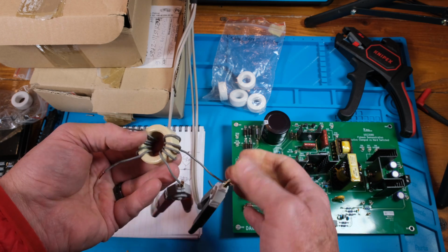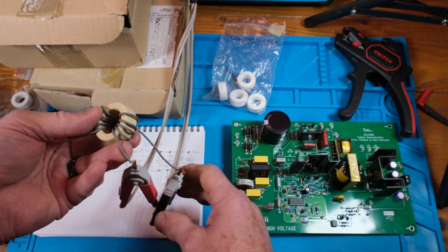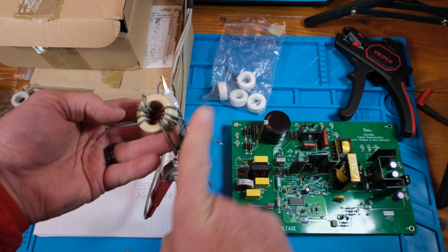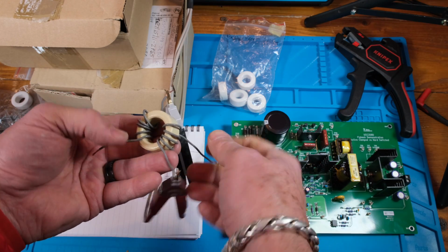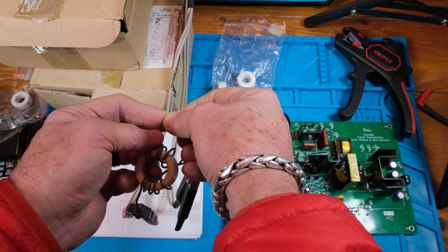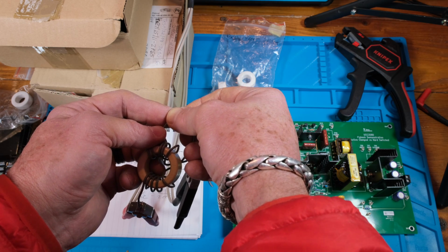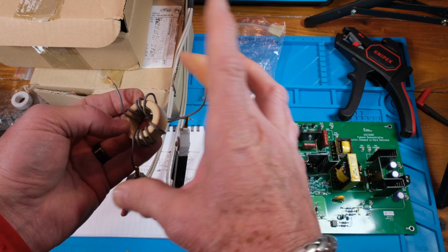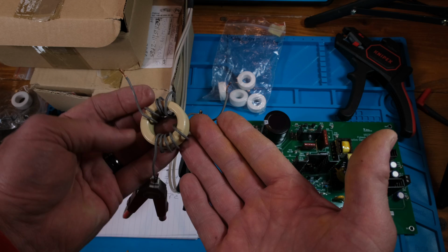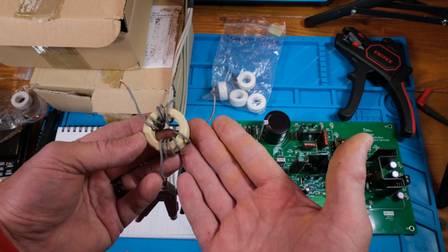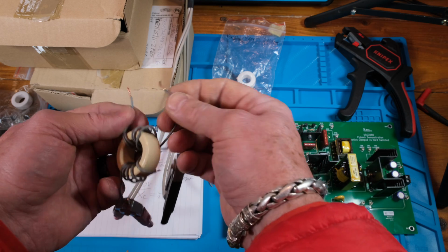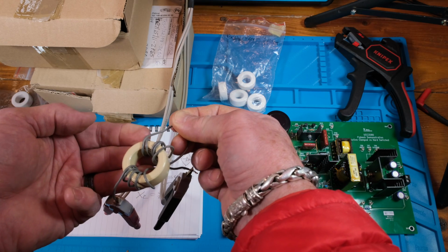So there we go. And now if I take this one, connect it over to the other core, so the current's going in this way and out that way. That's a differential current, right? And then I'll just short these, and I'm at 2.4 millihenries. So that's the common mode direction, and that's like 10 turns. So the way you calculate inductance is it's turns squared. So you get like 4 times the inductance when you put them in series.